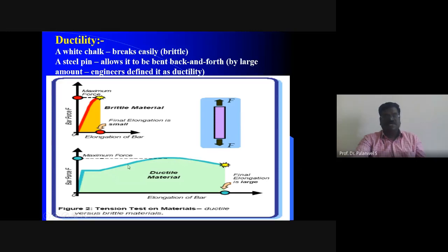So you are getting a beautiful stress strain curve for material like mild steel. That's why we can say mild steel is a very good ductile material. The best example for a ductile material is our mild steel, because the amount of inelastic strain is the measure of ductility. It undergoes large inelastic deformation without losing its strength. That is the measure of its ductility.